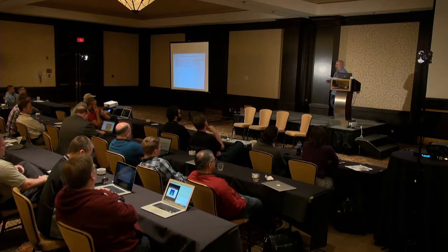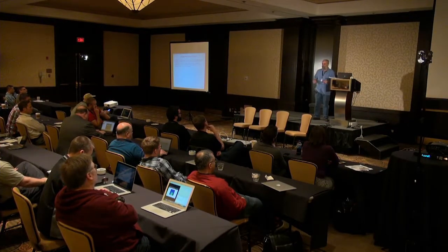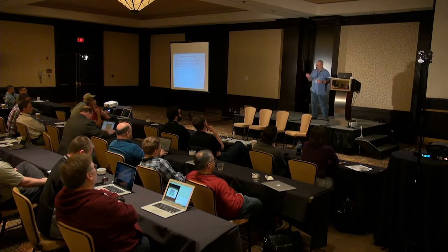Some of you might see some other small antennas by different companies like Murata and Taiyo. These are ceramic antennas. They are very small. They're nice because they fit nicely into mobile handset designs, but they are not necessarily the most effective.